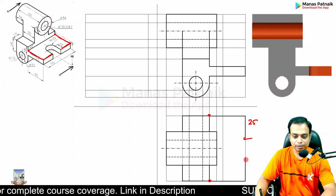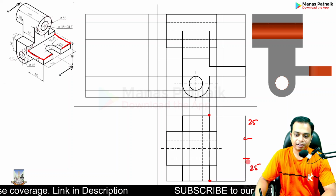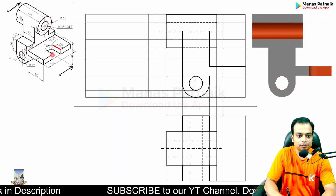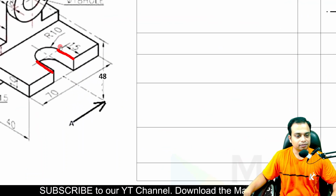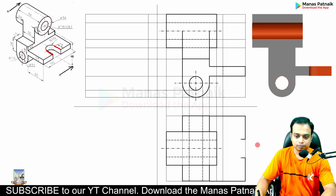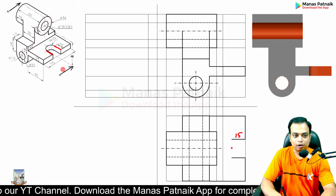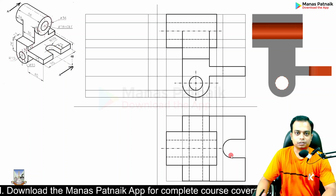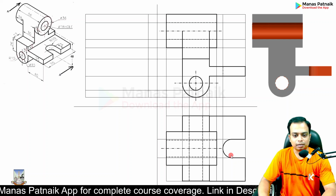You reach here, and from here again you go in the upward direction, stop at 25. Now again the work is simple. This is 15. Can I zoom in? That's 15. Here it is. Mark the center. Now with a radius of 10 millimeters, make the arc, semicircular arc. Done. Easy. Top view is also done.